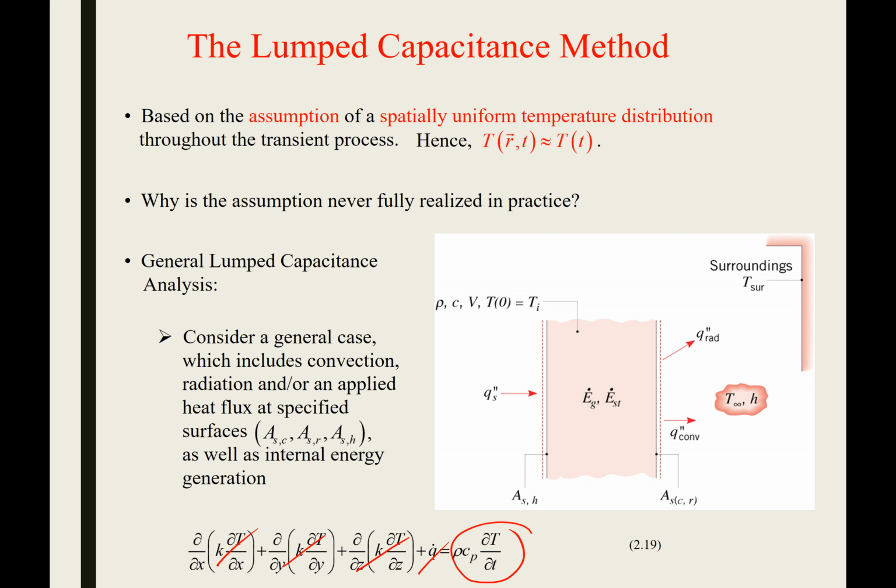So we introduced the first method and the simplest method for dealing with transient analysis of conduction, called the lumped capacitance method. So what's the key assumption we're making when we're using the lumped capacitance method? Yeah, Blaine? Great. So he's saying, yeah, heat transfers through the solid fast enough that you don't have any difference in temperature from the boundaries into somewhere in the center of the material. That's perfect. So basically we're neglecting any change in temperature with respect to our spatial coordinates.